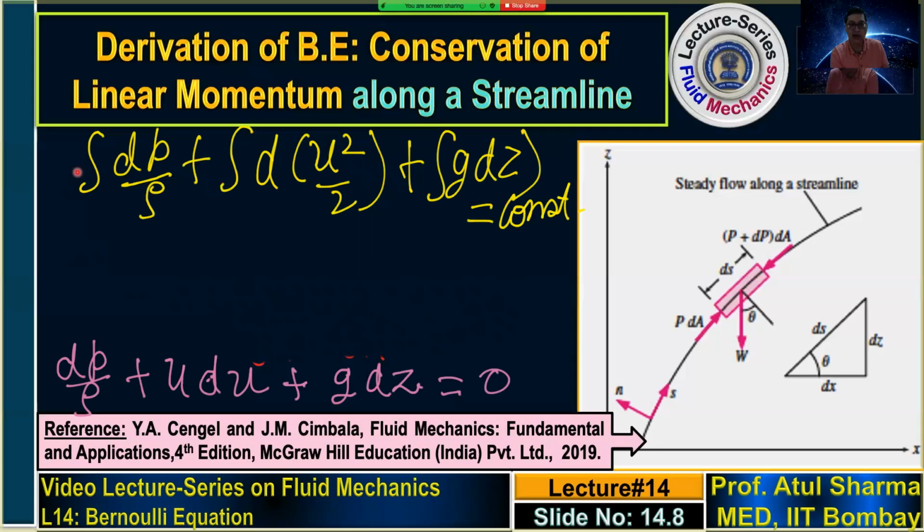The second and third terms are exact differentials because g is constant, so you can take it out of the integral, and the integral of g dz is gz, and the integral of d(u square) by 2 is u square by 2.